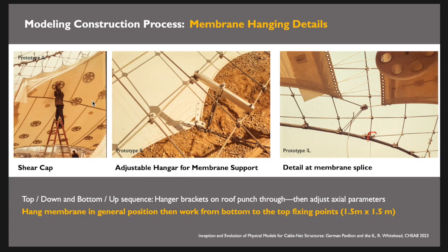You can't see any sags. You really can't see sags in this membrane. You have to be able to pull that tight, okay? But the membrane is going to behave differently than the cable net. So in order to allow it to behave slightly differently, both from a material and a structural perspective, you might actually pull it in different ways. It might not be a perfectly uniform gap between the cable net mesh net and the membrane itself, okay?